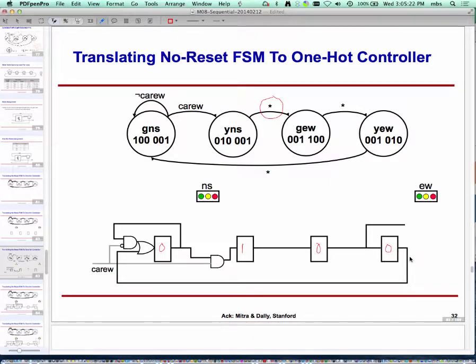Again, those of you who are missing it, these are all flip-flops. There's a clock here, there's a clock here, there's a clock here, and likewise there's a clock here. So all of those boxes are flip-flops. So when the next clock tick comes, what will happen is that since this flip-flop was 1, there's a 1 on this wire. So next clock tick, this 1 will move to this flip-flop. This flip-flop will read a 1. So next clock tick, this guy will go to 1.